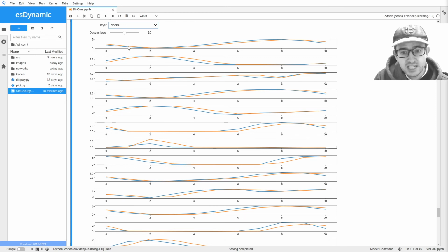Let's say the convoluted features for the two signals are pretty similar, and the original offset was completely removed. So here we started with two signals that were desynchronized, and what we can see is that the output produced by the convolution blocks are very similar for both signals, and so after that it's pretty simple for the last layers of the CNN to classify the two inputs in the same categories, because the two inputs have pretty similar abstract features at the end of the convolution blocks.